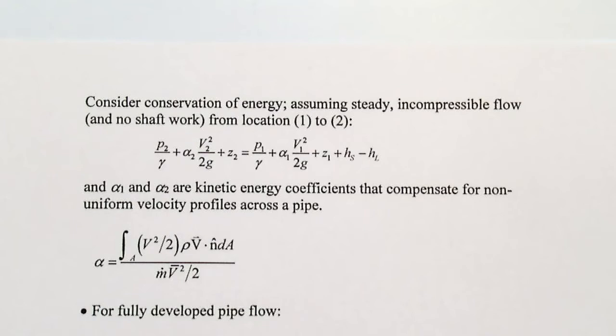So you have a pipe with friction, you have tau, and you have loss of energy. That's why the pressure, if the velocity is the same on both sides and you have a horizontal pipe, then Z is not changing from inside to outside, and also the average velocity doesn't change from inside to outside, but pressure changes, right?